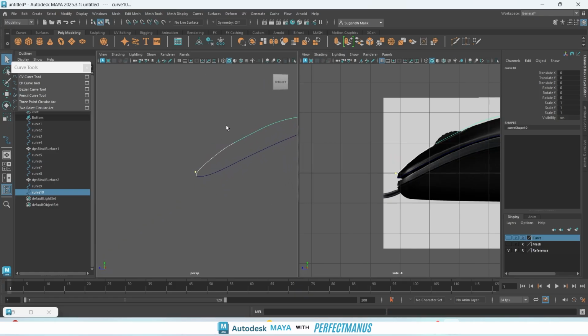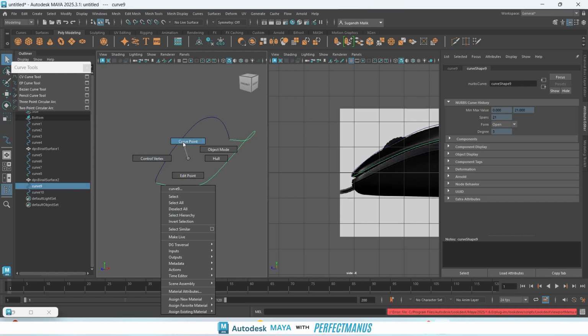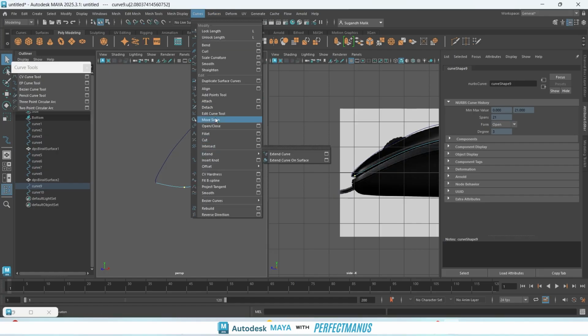So I guess this one is done. From here, we can see that it's not as smooth, but still we are trying to create something like that. Okay. Here, we only have two sides, so we need to cut either of these ones. Okay. So we want to create something as in this shape. That's why I will focus more on keeping cut here. So clicking on that curve and click on curve point to select a point, you get here and you detach it. Okay.